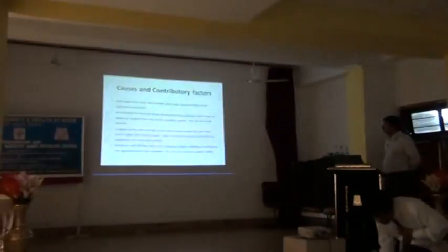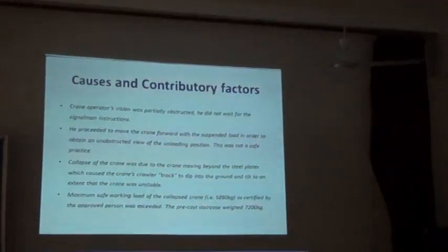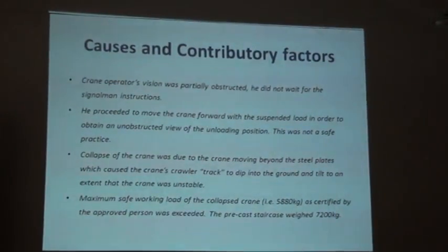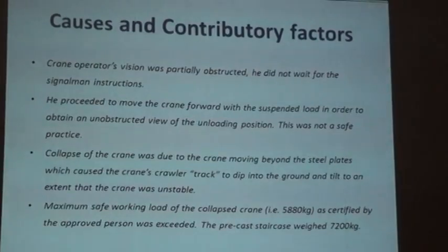Looking at this, the crane operator's vision was partially obstructed. He did not wait for the signalman's instructions. He proceeded to move the crane forward with the suspended load in order to obtain an unobstructed view of the unloading position. This was not a safe practice.